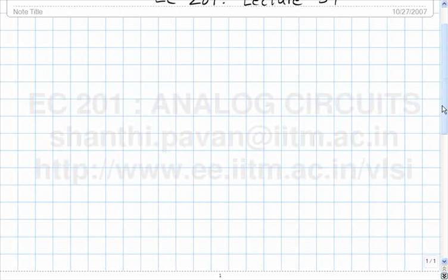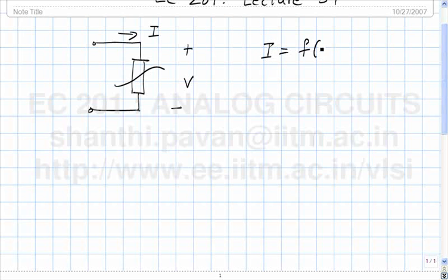You can relate the increments in the voltages and currents by a bunch of linear equations, which basically reduces to a linear incremental equivalent network. And we've always assumed that there are no memory effects inside the nonlinear devices. In other words, if you took a nonlinear device, we've always assumed that I is some nonlinear function of the applied voltage. Do you think there is some limitation with respect to this, or should this be sufficient to describe all varieties of nonlinear one-ports?